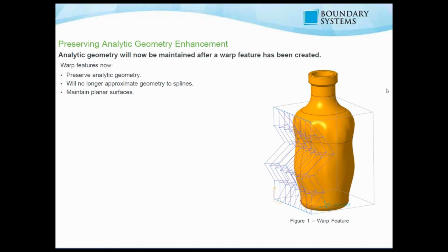Periodic curves have no concept of start or end point and should be created to be as seamless as possible, whereas non-periodic curves are typically two halves of a curve, and then you have the ability to define the tangency between those two curves at that point.